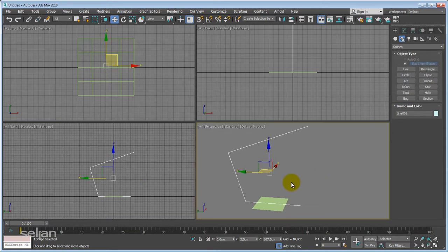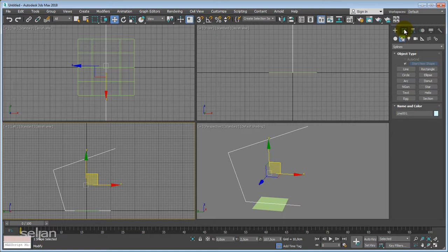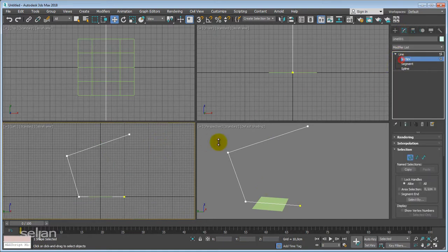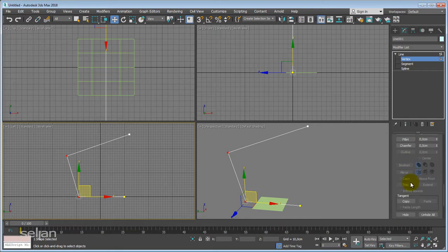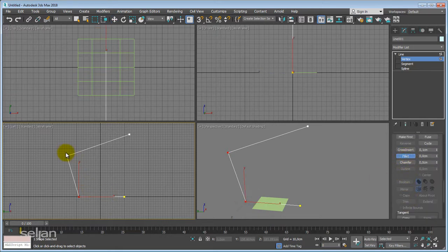So okay, now once we have it, it's not there yet, so what we do need is to fillet these points here. So I'm going in, look for the fillet. Points are selected previously, and when the fillet is activated, now I can go in and use it. I'm holding down the left mouse button and dragging the mouse upwards, and as it is, I will stop before these 2 points in the middle reach. Okay, because if they reach, then that can cause an overlap.